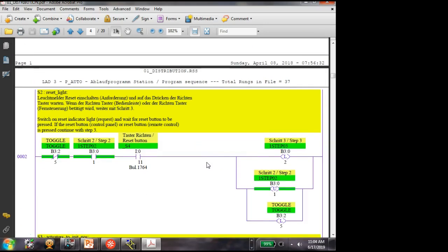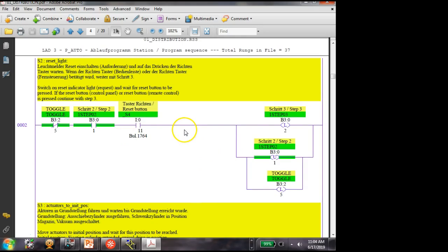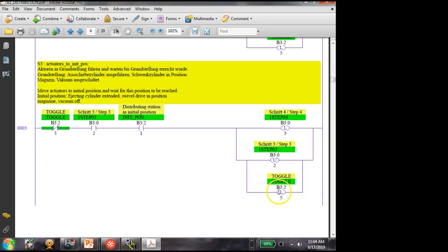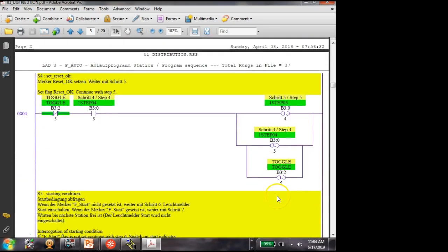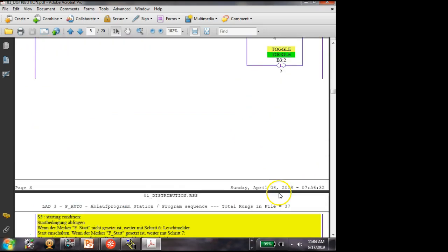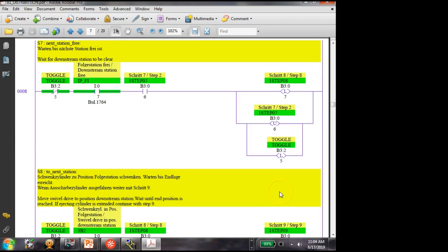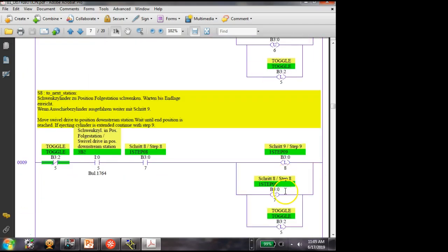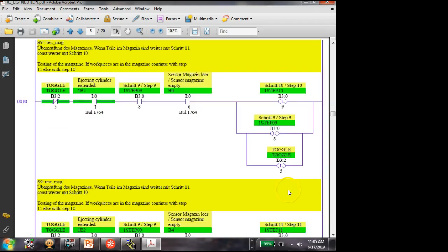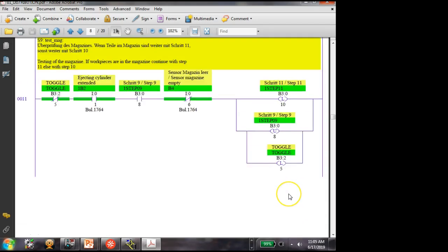This is where they're basically trying to figure out if everything's in the right position, but they latch, they unlatch, they latch, they latch, they unlatch, they latch, they latch, depending on the sequence. And look how many they're using in just this module right here. And they're not even generating outputs. All they're doing is just making decisions on when to generate outputs. So these scan faster than a 3-wire control or a memory, and they're a lot simpler. Are we okay?